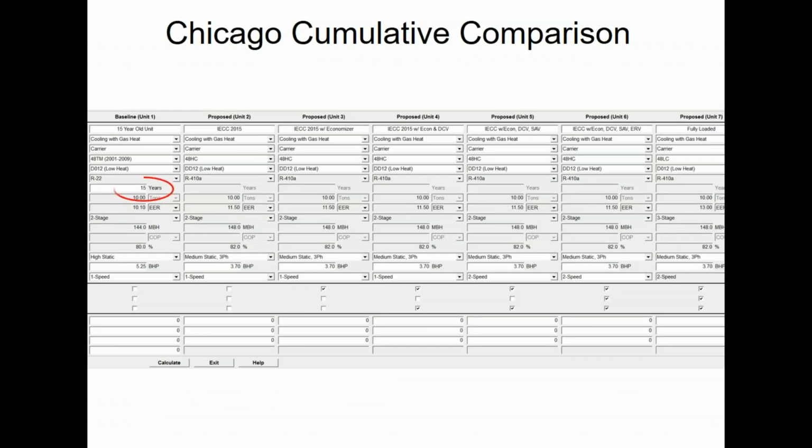I also want to point out that I could take all of these things we talked about and add them all up. And if you look at all my little software calcs we did throughout the presentation, you'd be like, damn, Ryan said we can save 105% of the energy. No, it doesn't work like that. These things overlap with each other. So if I put an economizer in, that affects my DCV savings. And if I have a staged air volume, it affects my economizer savings, and so on down the line.